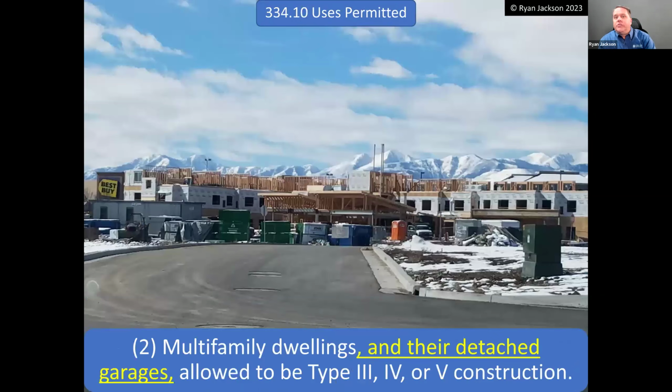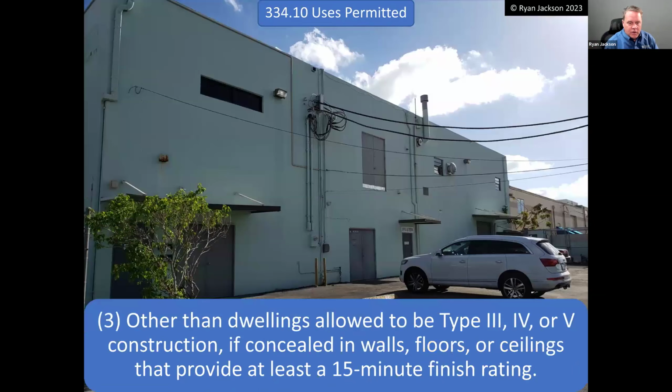Can you use it in multifamily? Well, yes, you can use it in multifamily if it's allowed to be Type 3, 4, or 5 construction. If it's Type 1 or 2 construction, right, concrete and steel, it's a non-combustible building. We don't want combustible wiring methods. We want to have steel conduit in there or something, right? So you can't use NM cable in multifamily unless it's permitted to be Type 3, 4, or 5 construction.